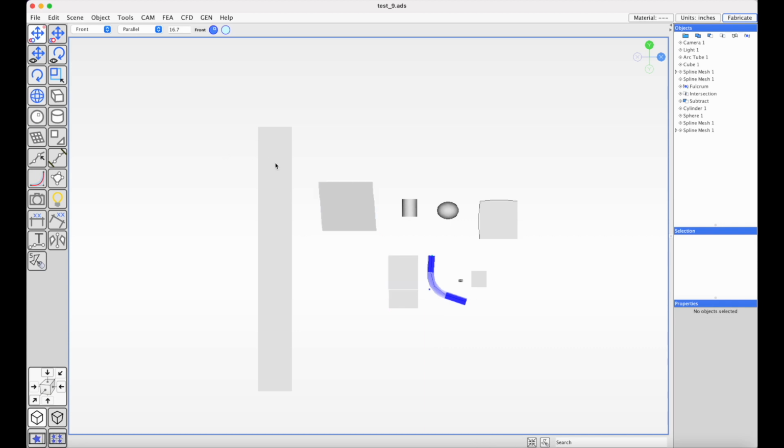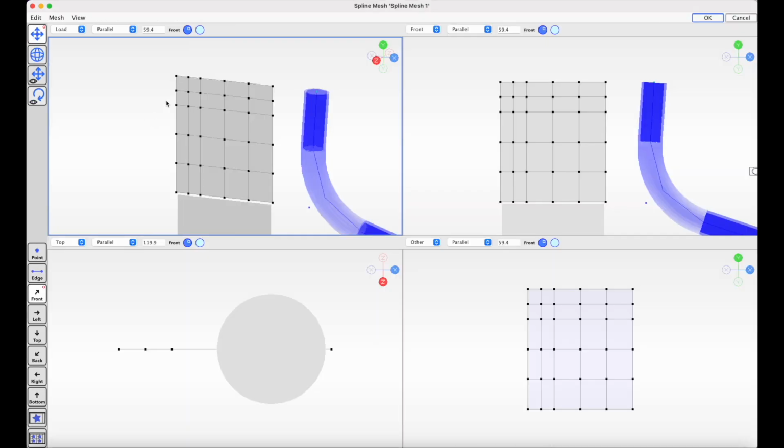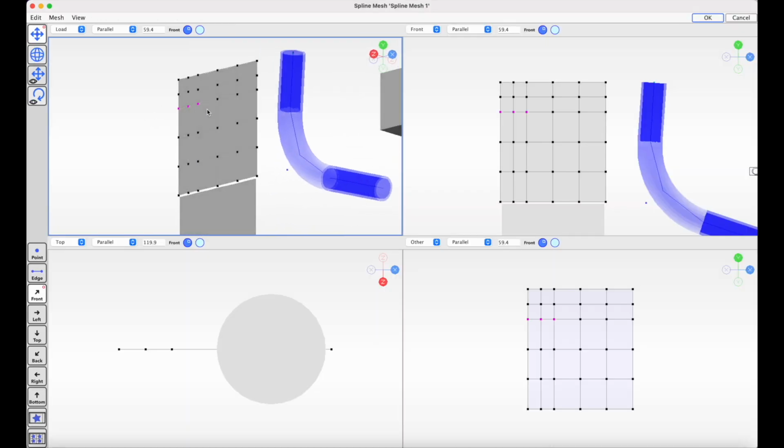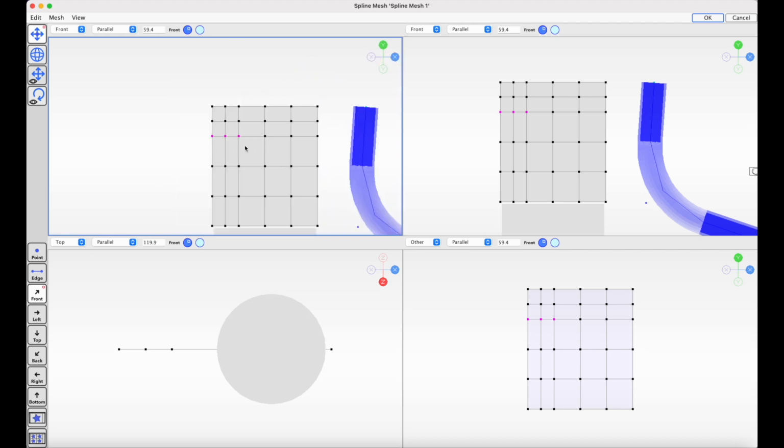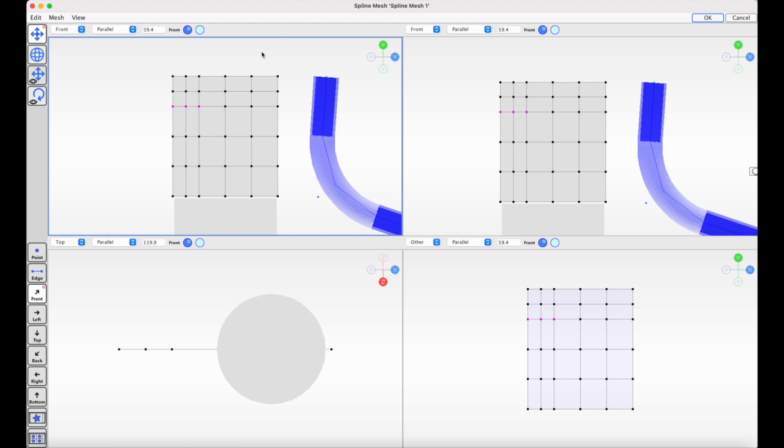the items selected. In the edit view, you can make a selection, rotate about the selection, and if you change the view direction, it will center the view on the selection. And if you hold either Shift, Control, Alt, or Command keys and a direction, it will center on the object being edited. An update in this release also adds support if you select points and hit the Option key,